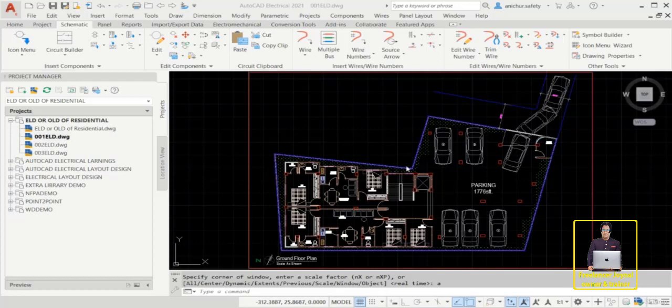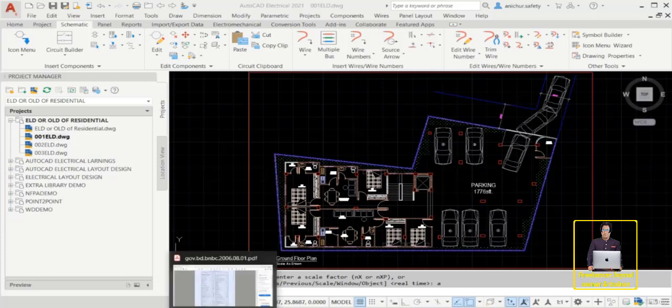Now in this floor plan we put HDB board, DB board, switch board, outlet socket, fan, light, etc. Too often the person in the field does not see the written specification but sees the drawing and the legend. If the symbol for a floor convenience outlet appears, for example, the worker knows what the symbol means but not which of the 50 available combinations is required unless it is specially stated. So these legends are very important, I am talking about again.